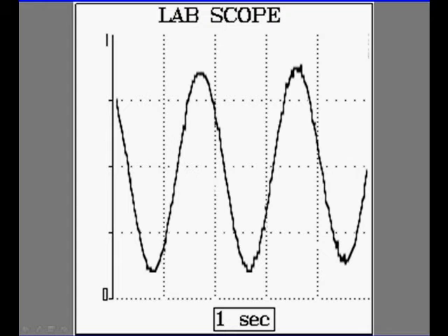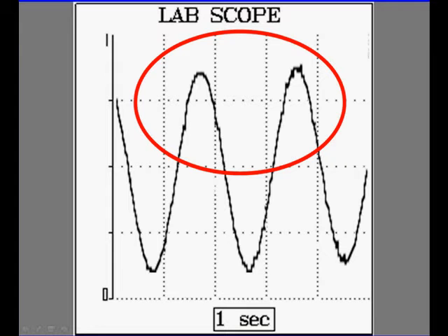This is a perfect oxygen sensor waveform. And I say that, but it's probably almost perfect. Nothing's perfect, right? But this particular oxygen sensor waveform has been used by us at the Research Center for years to show you what perfect should look like. Now, when you look at the tops, or the rich side of the oxygen sensor, it can help determine things like basic engine condition, leaking EGR, too rich conditions. And that's important because just looking at the oxygen sensor can tell you, hey, I have to go do an EGR test. I have to go do